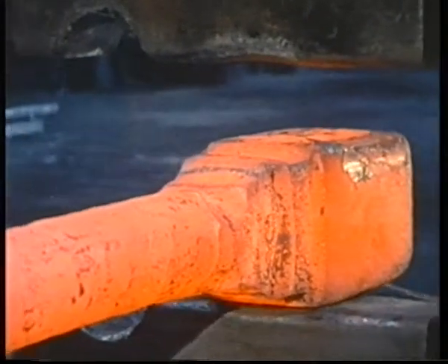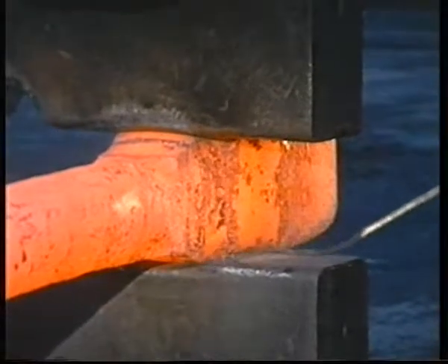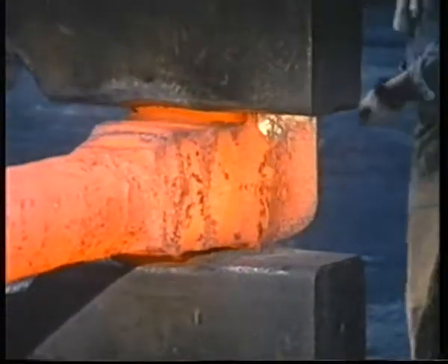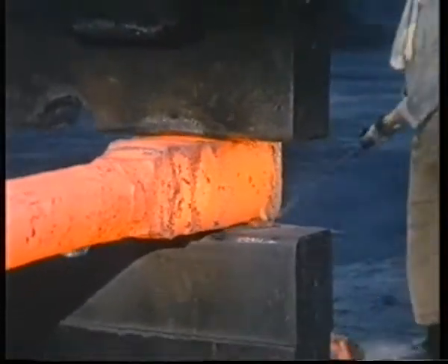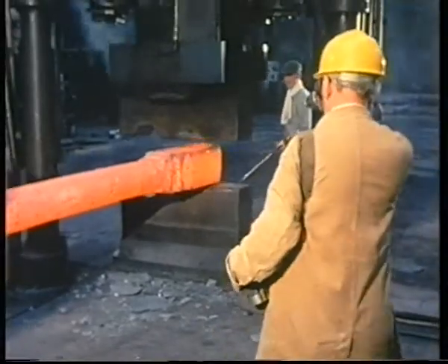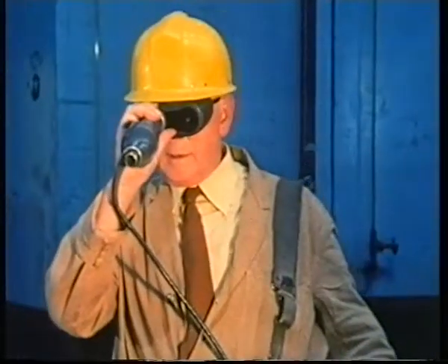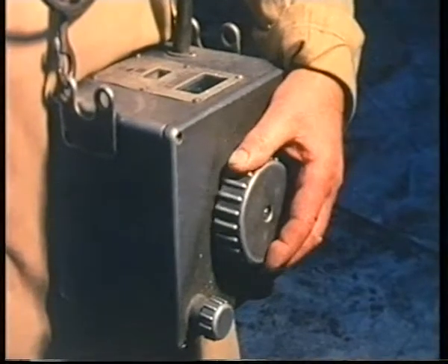Here's another process where temperature is important: hot forging. It would be difficult to use a thermocouple here. However, in this case, the temperature can be measured by another device known as an optical pyrometer. It looks rather like a telescope, and this is what he sees when he looks through it. The small disc in the middle is the color of the component. Running through the disc is a piece of wire, which can be heated by an electric current controlled by this knob.